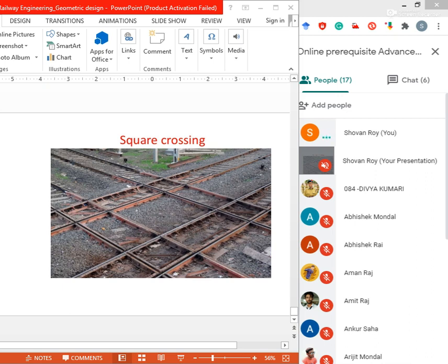There should be provision of facilities for dealing with special traffic such as pilgrim and tourist traffic, parcels in wagon loads, livestock and motor cars. Stabling lines, washing lines, sick lines, etc. should be provided as per requirement. So these are the requirements of railway stations, yards, selection of site of railway station, purpose of railway stations.